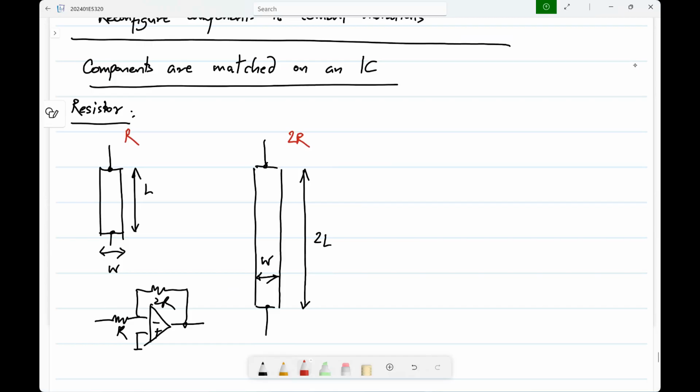No, it's not okay. Metal or you have multiple metal layers and you can make connections between them by essentially poking holes and filling them with metal. Okay. So you have on an IC, if you want to make connections between different layers, this may be polysilicon resistor, and to connect to this, you will have some plug and then another metal layer. Okay.